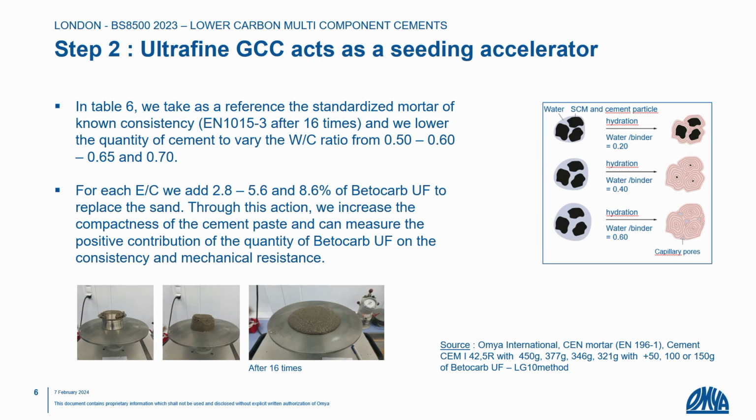This graphic on the right is interesting because we can see, at the end of the day, the effect of the water concentration, but we also see the effect of the addition of the ultra-fine ground calcium carbonate, because we increase the total powder content. That is to say, we play on the paste thickness of the system and also on the water film thickness of the system.